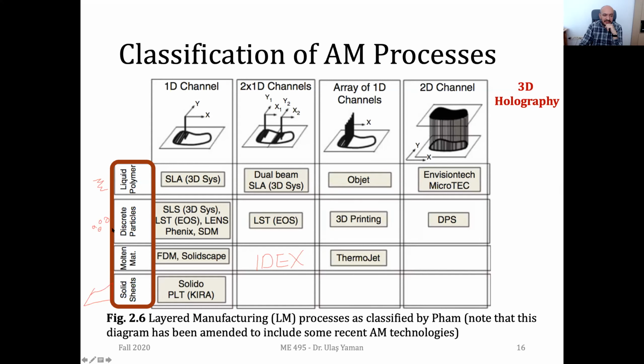So you say you are in the second row, you are around here, right? Yes. But how can you do that? Since in sintering, you need to increase the temperature of these powders and join them together. We'll discuss the fundamentals, but here let's say that in a sintering operation, if you have two powders, then very similar to powder metallurgy, you increase the temperature up to some intermediate value of the melting temperature, then they fuse together and they stay together after that point.